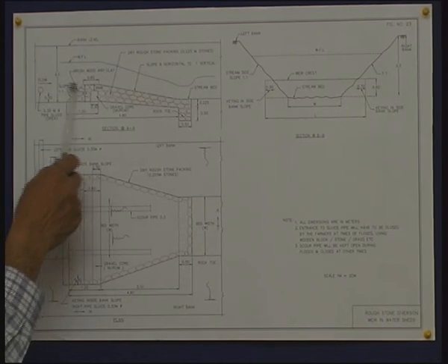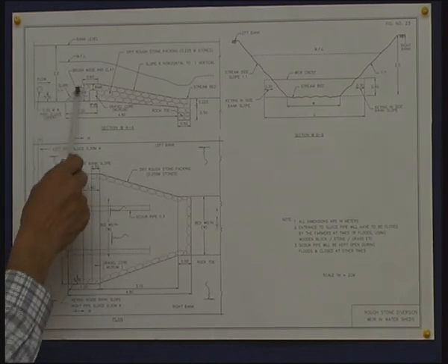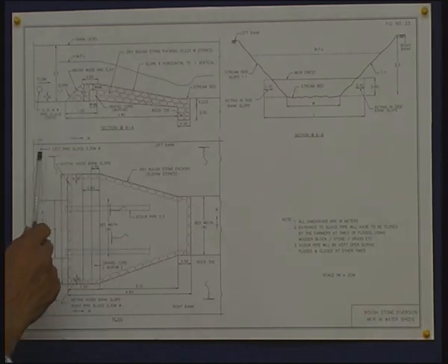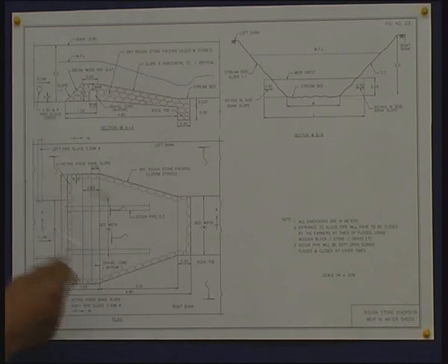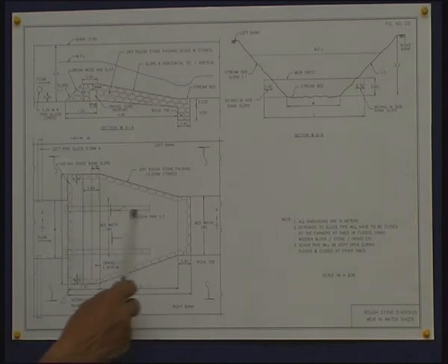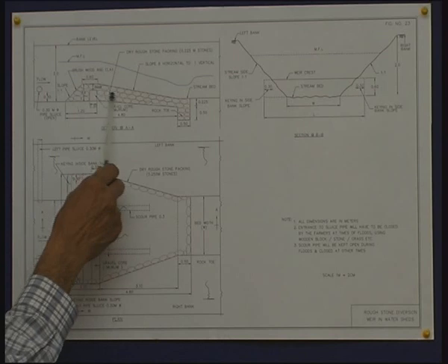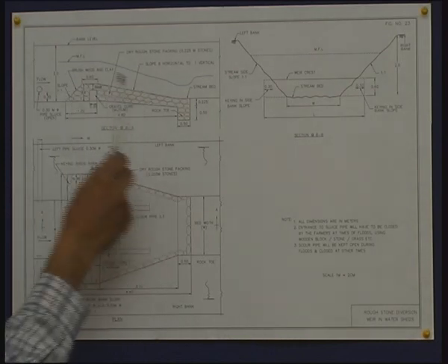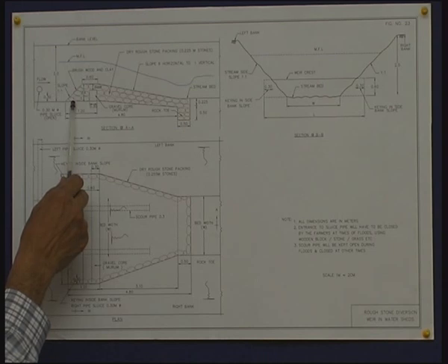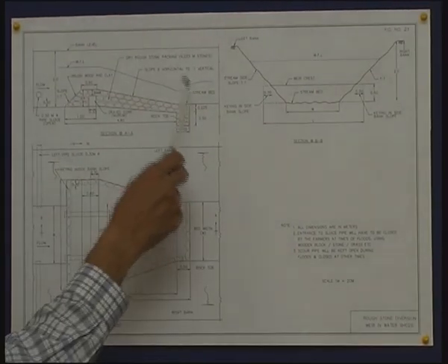Now, we discussed about the siltation. If it is silted up to this, the sluice also will get blocked. So, we have to clear the silt deposited on the upstream side. A method of removing the silt, what we call scouring or ejection of silt, can be achieved by placing two scour pipes, one pipe here, another pipe here, and in the section it will be something like this, one pipe at this level, and this pipe will be about 0.3 meter higher than the bed, and when this is kept open, this silt here will get flushed out.